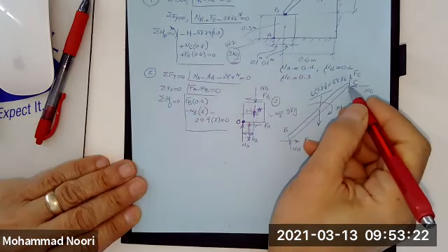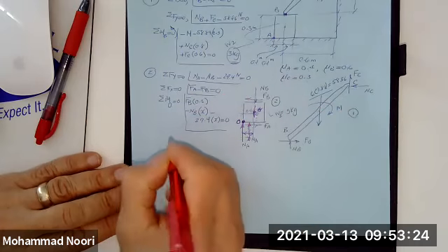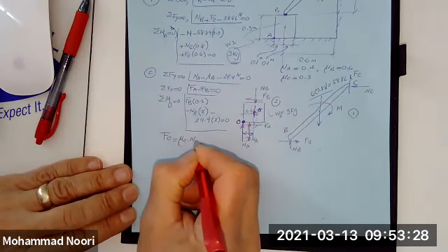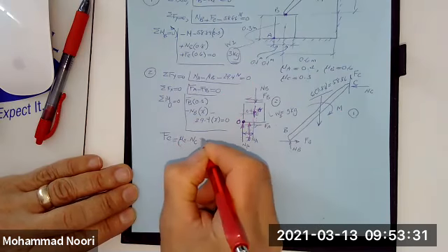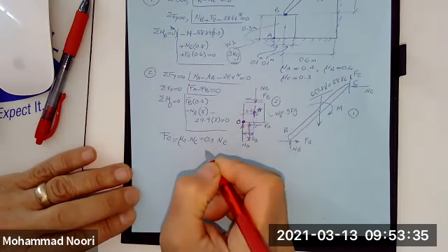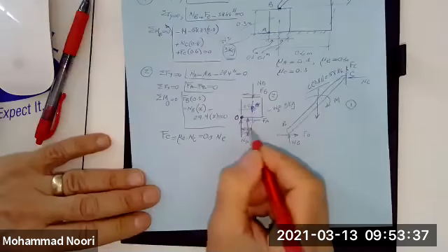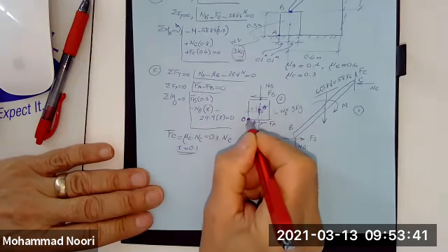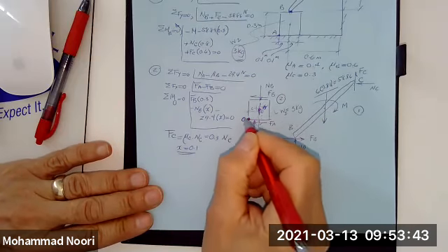So we know that the maximum force that exists here, F_C, would be mu_C times N_C, which would be 0.3 times N_C. And this X, which I said, is 0.1, because that's the point that this block will tip.